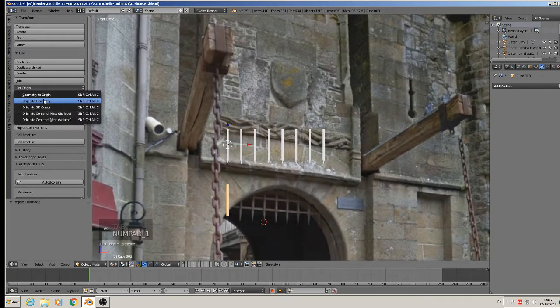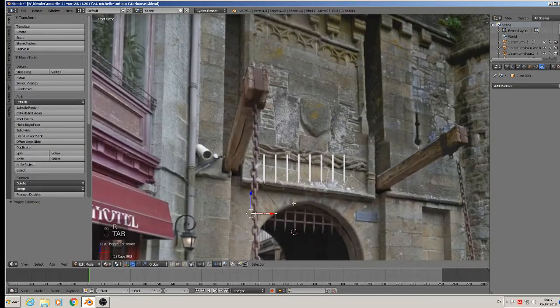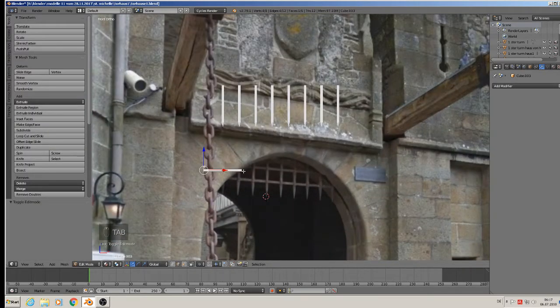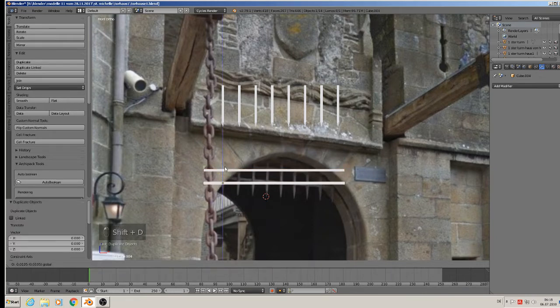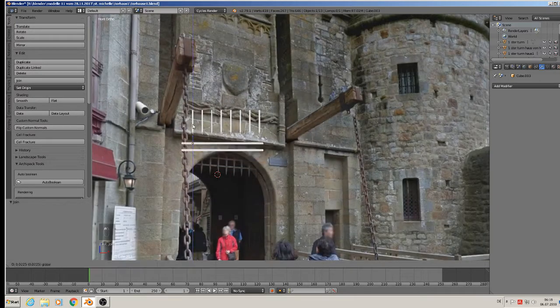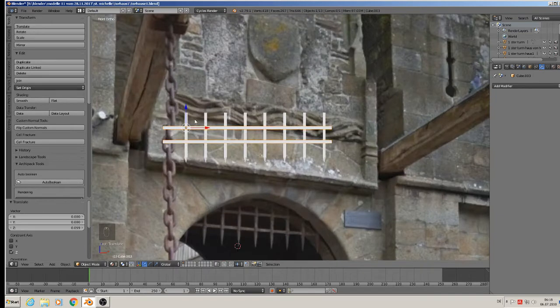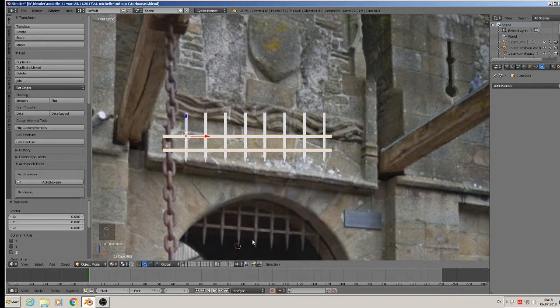We set the origin to geometry, rotate Y at 90, and get this longer. We have only 2 of them, so Shift D simply and place it there. Then we join them together as one and place it over them. We'll see them much longer, so we will make that.